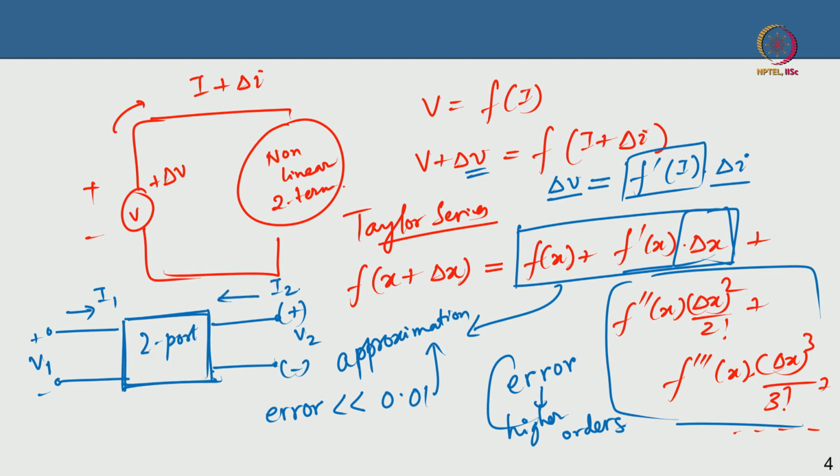Okay. So now for any change delta V1 here, I am going to get delta I1 here, correct, or maybe I can write a small i here, and for any delta V2 here I am going to get a delta I2 here, right. So now actually this current that is flowing, I1 for instance, it's a 3-terminal device like a transistor, it's a 2-port network. So the current I1 will actually depend on both V1 and V2. Now I cannot say that it just depends on V1 because it's connected. It depends on both sides actually.